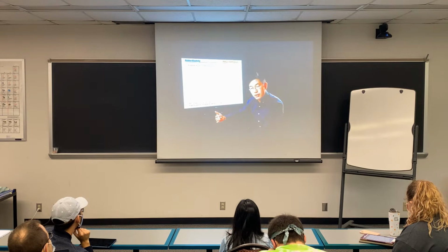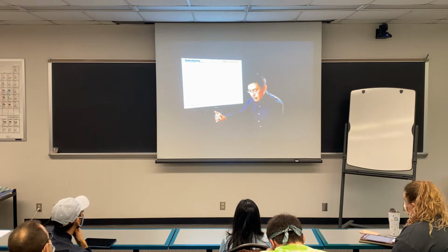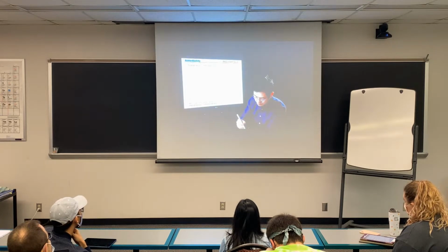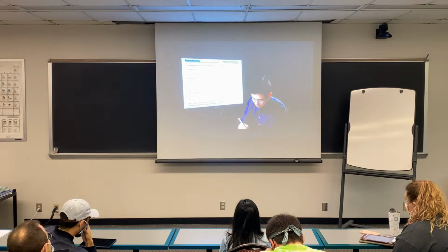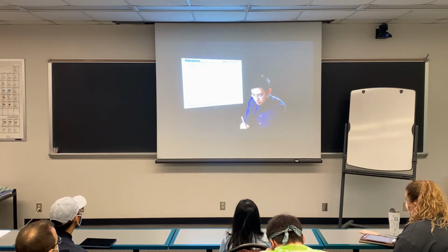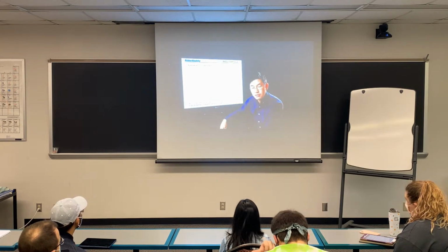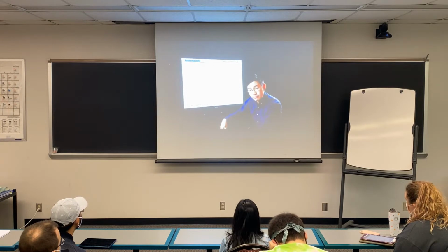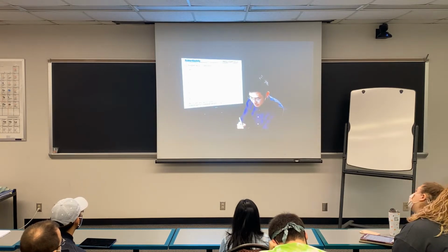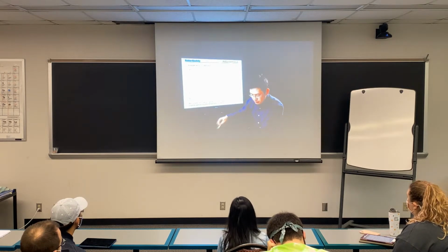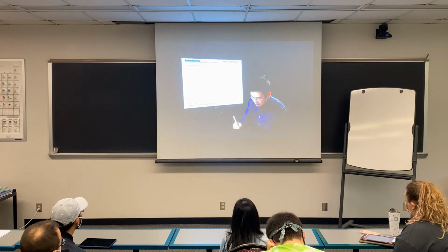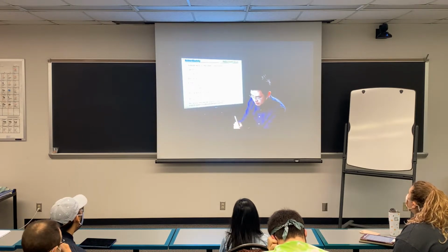So how do we get C1 and C2? We get them from measurements of stress and strain. We measure the stress and the strain, but instead of plotting stress versus strain, we modify the stress to stress divided by lambda minus 1 divided by lambda squared. This is the new y value, and you plot it against 1 divided by lambda, which is x. Again, look at the equation y equals a plus bx.